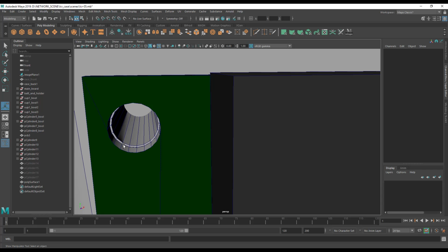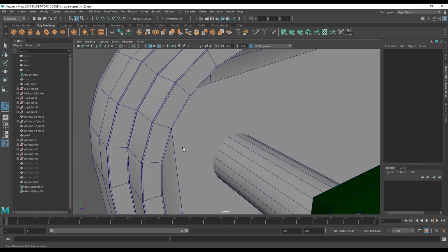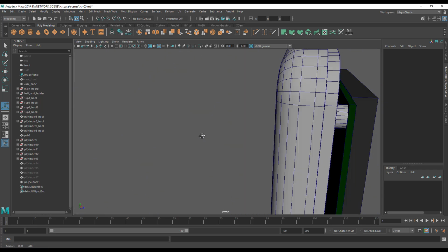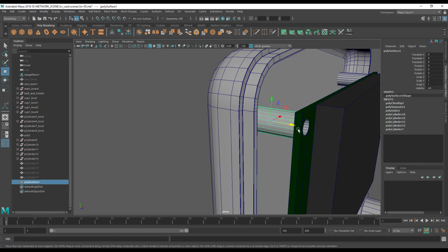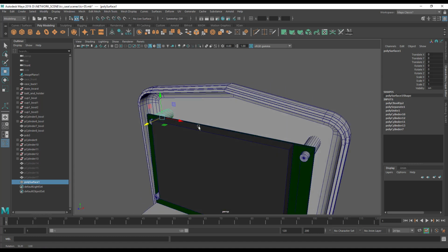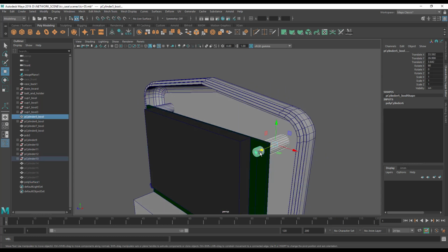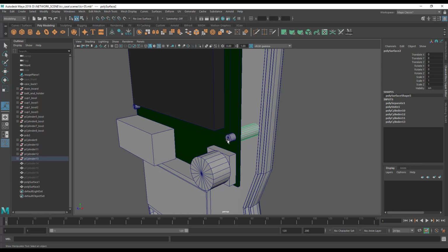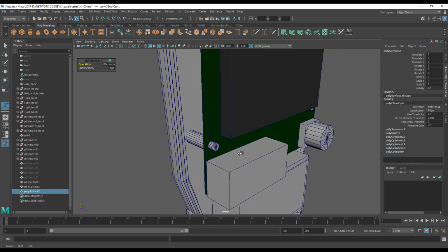And you should see our support pillar now has a hole in it that goes right through. It's slightly smaller than the 3mm hole here, which is absolutely fine. It's exactly as we want it. And I'm going to pull this up, and you'll see that it still has lots of support material on it to support the back of the circuit board. So just go ahead and use G to repeat the last command and boolean all of these things.